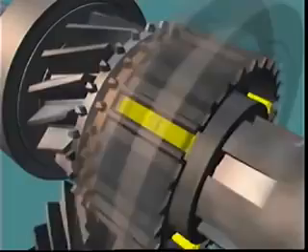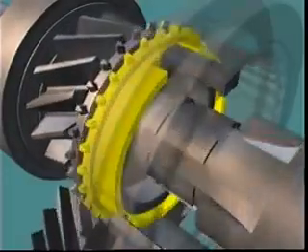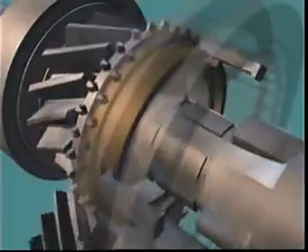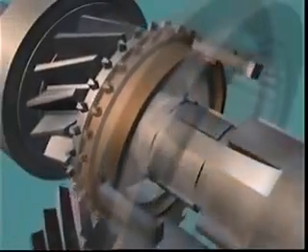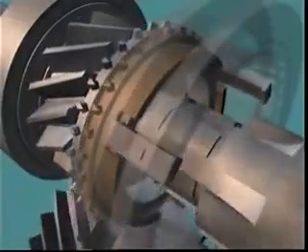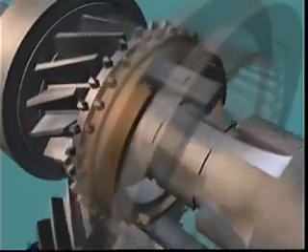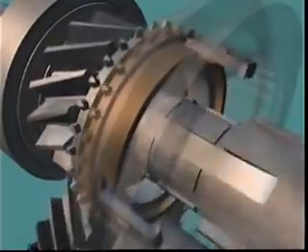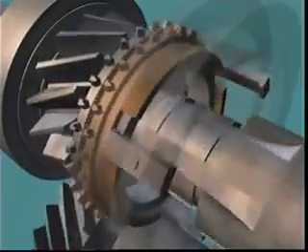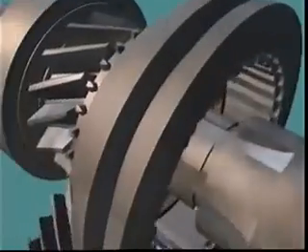When the sleeve is moved to select a gear, the spring-loaded inserts move the balk ring into contact with the conical face of the gear. The grooves in the face of the balk ring help to break through the oil film, and the difference in speed of the two components causes the balk ring to be dragged around with the gear to the limit of the recesses, where it is held by the inserts. Since the teeth of the balk ring are now out of alignment with the teeth of the sleeve, this balks or prevents the sleeve from moving over the ring into engagement.